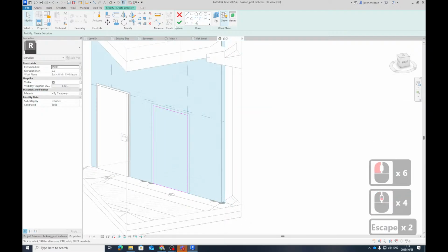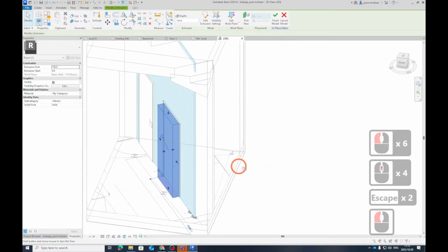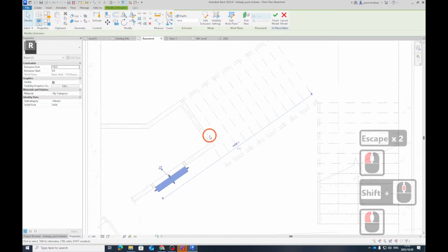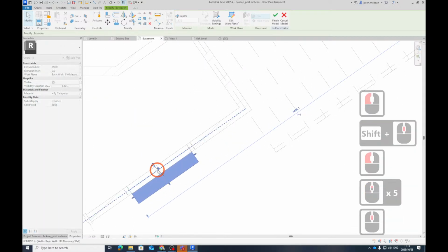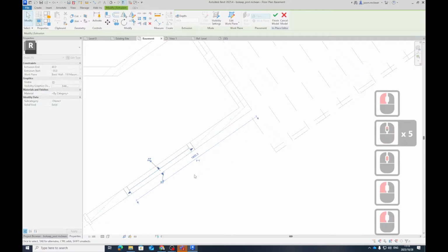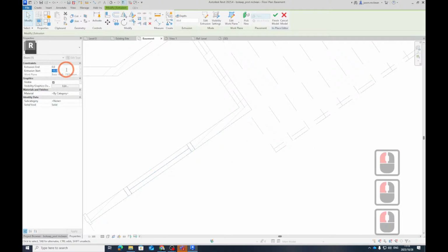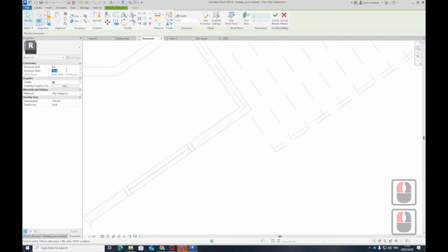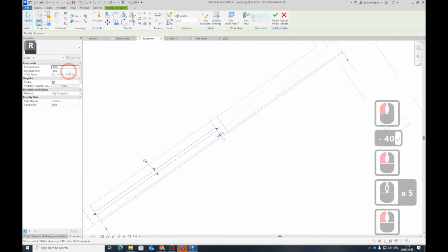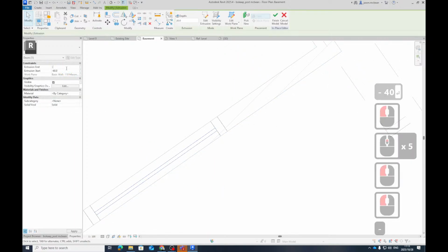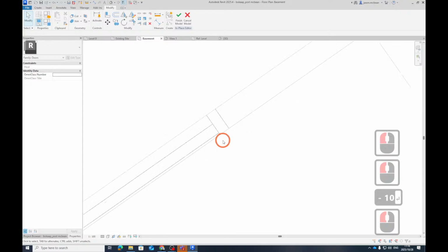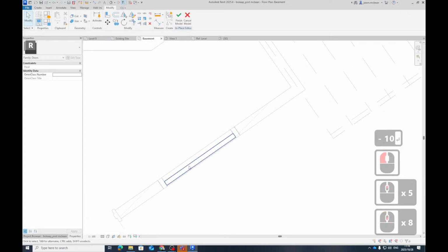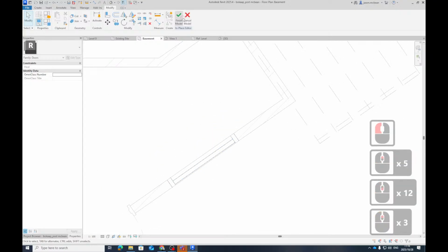So now, if I create this extrusion, it's going to make a thick door. But if I go back to basement, and I move this frame inside here, remember where this plane was working from? So if I say minus 60 and I go minus 10, the extrusion will work within. I did say minus 10, I don't know why minus 10, anyway. You see it's offsetting at minus 10 from that? So there's my door, finish.